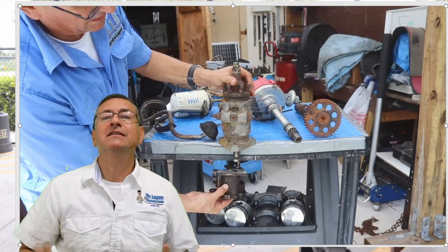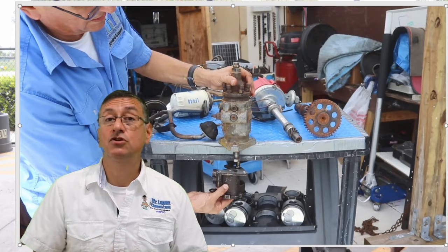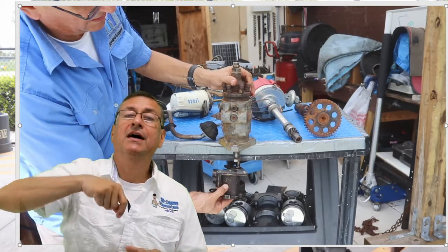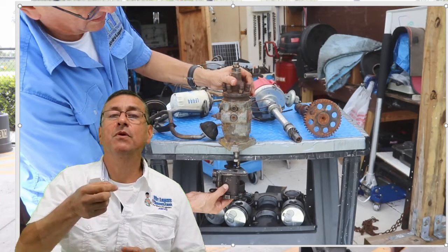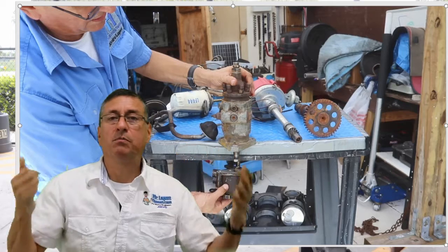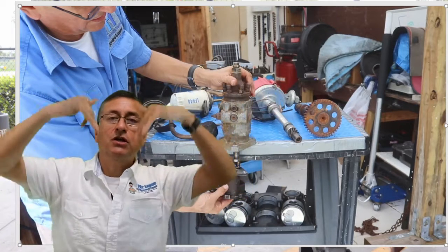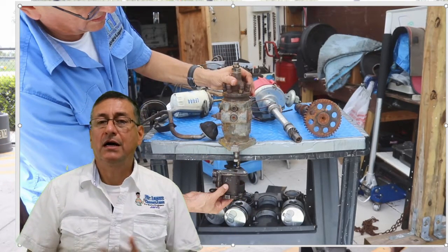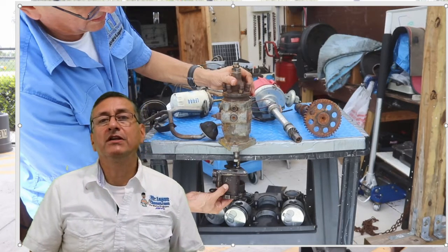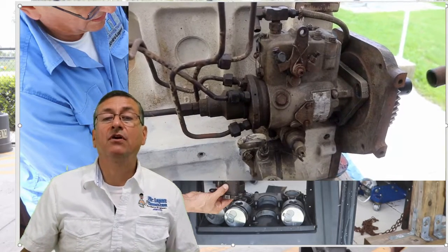This is an example. This is a fuel injection pump, a rotary fuel injection pump. In some engines, you can install that pump vertically, and if the pump is vertical, the shaft of the fuel injection pump engages with the shaft of the oil pump. The oil pump sucks the oil and circulates it internally in the block and the head, and the oil returns to the oil pump by gravity. This is in diesel.